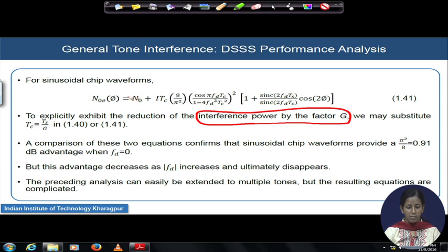In a conventional system, the same equation holds good, but you consider T_s instead of T_c, and here your whole period is getting divided by the period of capital G. So, we claim that this kind of structured communication system is highly resilient with respect to the jamming signal compared to conventional communication systems.